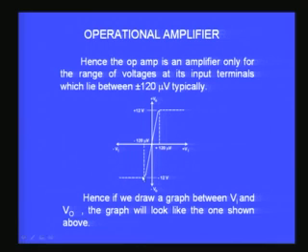There is a saturation at minus 12 volts, and then there is a linear portion crossing through the origin, and again I have a saturation at plus 12 volts when I come from very deep minus voltages to very large plus voltages. This is the characteristic I will get. But I would perhaps explain to you, this has got very good applications, especially non-linear applications of the operational amplifier are very useful.